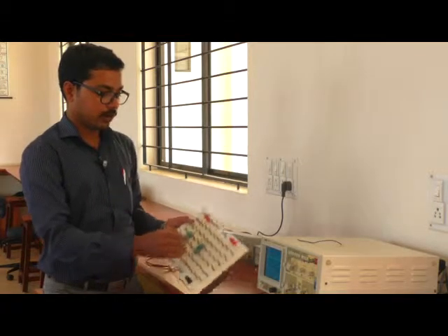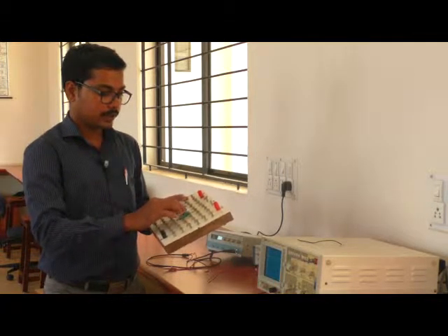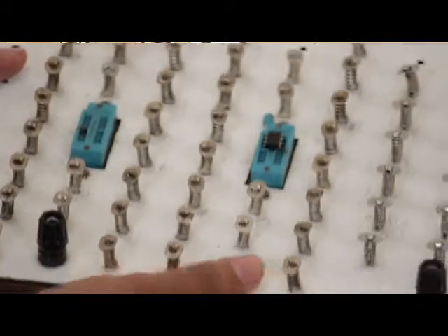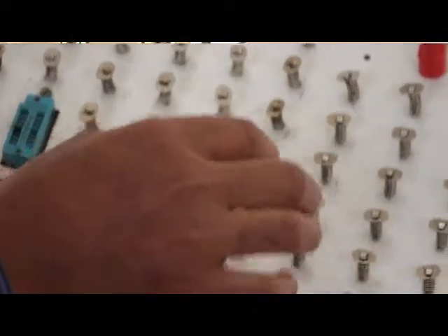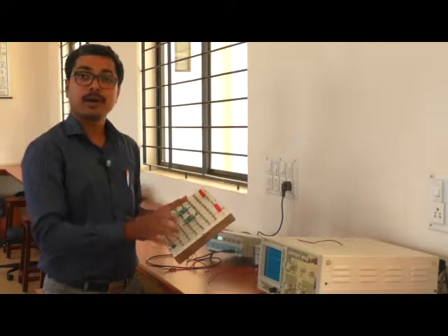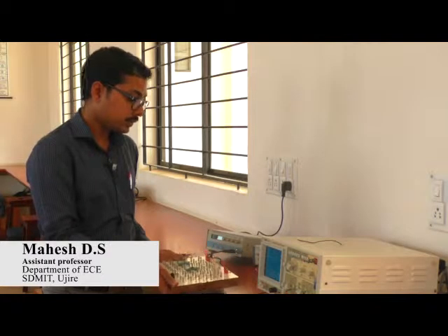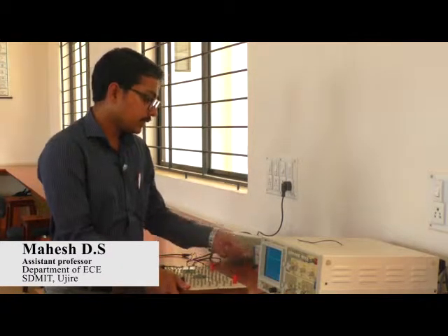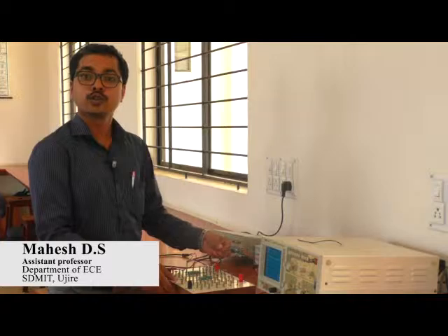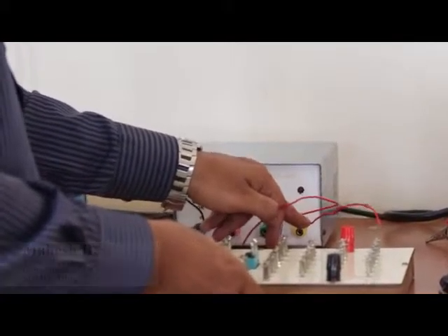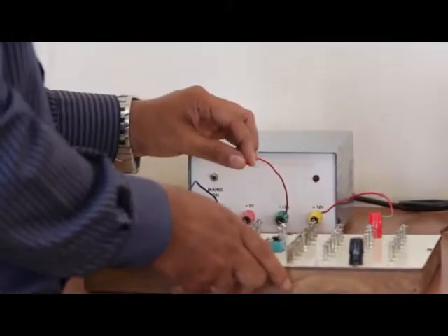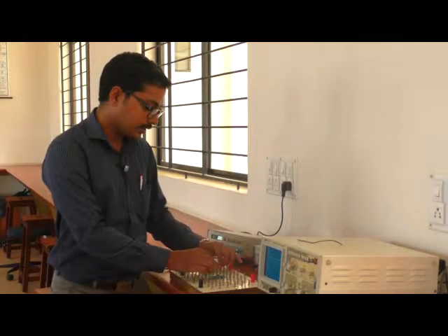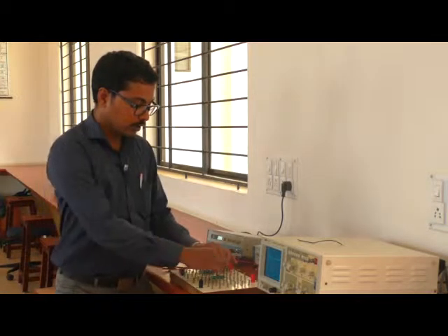So I'm taking this IC, mounting it on the IC holder and locking it. Now the IC mounting part is ready. Now I have to make the necessary connections so the OPAMP can be used as a voltage follower. First, let us connect the supply voltage. There are 2 supplies, minus 12 volts and plus 12 volts. Minus 12 volts is called VEE, that is a negative biasing voltage for the transistors present in the IC. So it is connected to pin number 4.